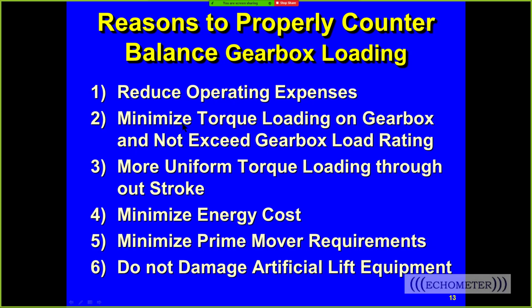You will minimize your gearbox loading and not exceed your gearbox rating. Ideally, if the pump unit is properly sized, you'll have more uniform loading throughout your stroke, and that will contribute to more uniform speed and higher efficiency, and that'll lower your energy cost, less power, and it'll minimize your gearbox size requirement.